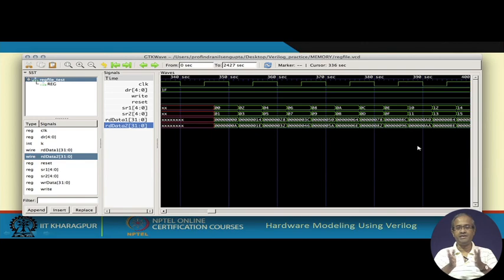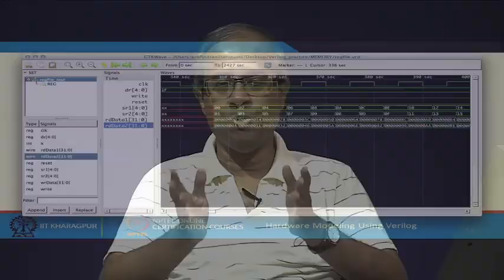So, you see in this way you can model a register bank or a register file, and you have seen through the test bench that actually you are able to read and write together at the same time. Okay. So, we will see some more examples of register banks later when we talk about more complex systems that involve something called pipelining, but this we shall be discussing later.